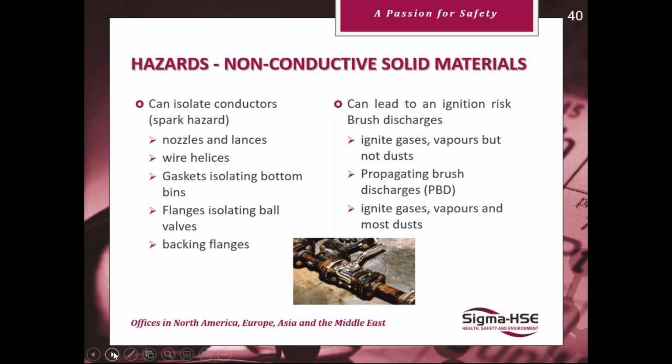But even though you may have a dust with an MIE of 1 millijoule, brush discharges cannot ignite it. This has now been proved. You could get up to propagating brush discharges with huge ignition energies. They can ignite gases and vapors, and most dusts. Propagating brush discharges can basically ignite anything that's flammable.